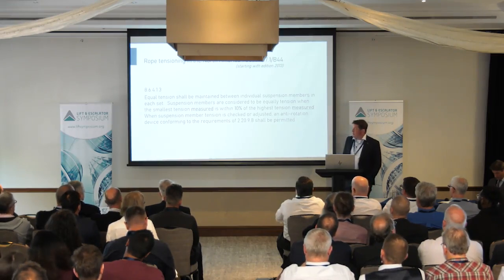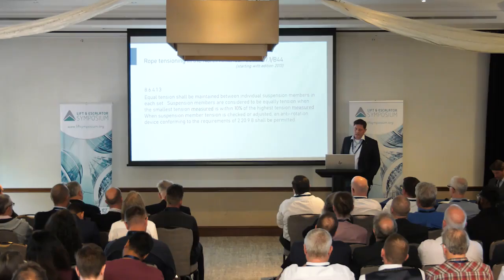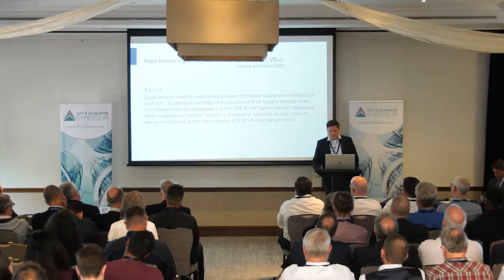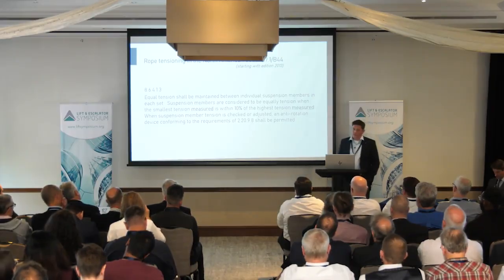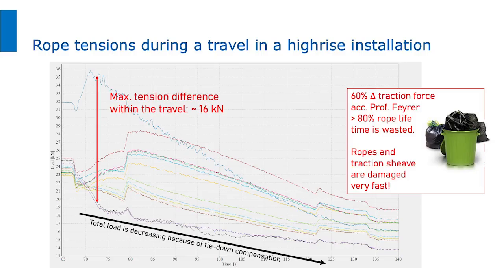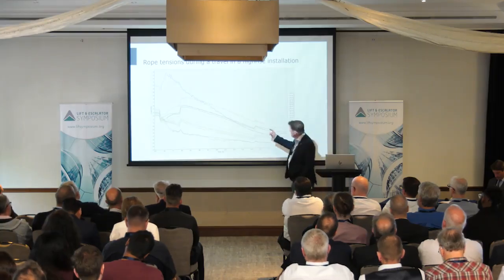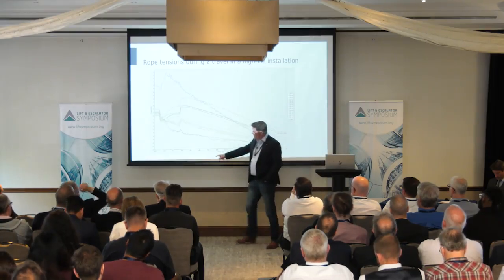Bad tensioning will cause wear in the first step. In the second step, for sure, it can cause a lack of safety. That is a real measurement, and that is something modern overload controllers, for example, can recognize and send alerts for. That is a measurement from 12 ropes over time.